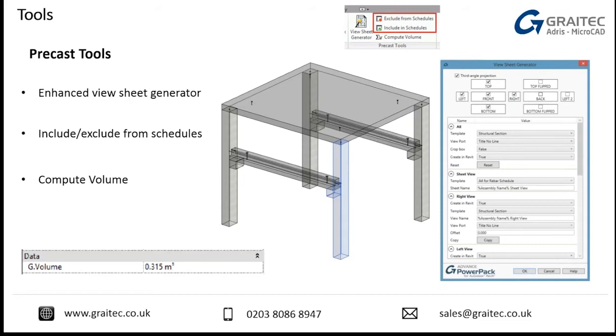Okay. We've got an ability to exclude and include from schedules, so there might be certain elements that you don't want to schedule all the time because it's part of an assembly. We can actually control that. We've also got the ability to compute the volume of an assembly as well. So if we want to know the volume of concrete for that assembly, then we can start to get the exact volume back out as well.